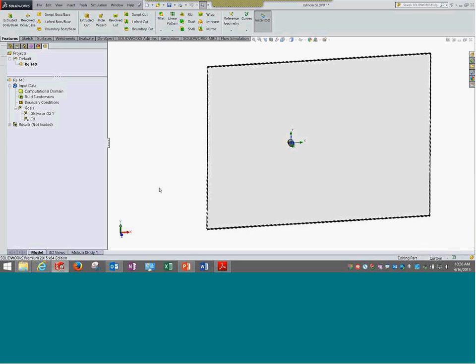But there are two things. Number one, this shows you how to use the dependency option, or how to give an equation in the software. Number two, it also gives you flexibility. Assuming all other values are known, I get a copy of this setup and just change the Reynolds number from 140 to 60. I changed the absolute value in this equation from 140 to probably less than 60, any value, and want to check the iteration. That's it. So it becomes easier using these equations. You can play with the parameters that you know or are comfortable with.